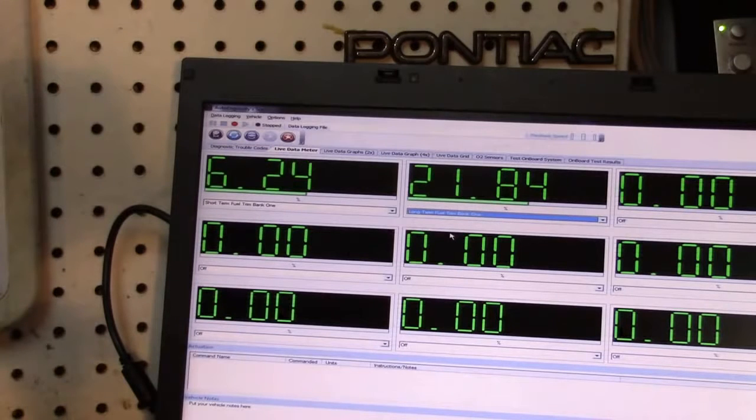What is that going to do you think? Well, if you think about it, that is going to cause that fuel pressure regulator to close. The fuel pressure increases, but the engine is still at idle. With a higher fuel pressure, there will be more fuel injected per injector pulse. That would, of course, richen the mixture. So let's go ahead and see what happens.